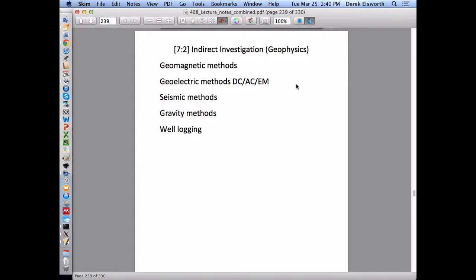So drilling is one way to do it. It gives you only a linear profile in a very restricted area. I'm not sure what density. You saw the density for Smithville. Maybe there was a drill hole every 20 feet away from each other. And so in that particular site, it may be 20 meters, so it's 60 feet deep. So it's a trivial depth, so you can afford to put these things down wherever you need. If you get to be working on a larger site, then maybe you can't afford that density.